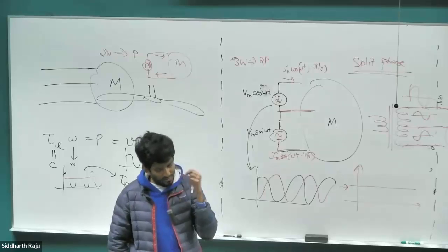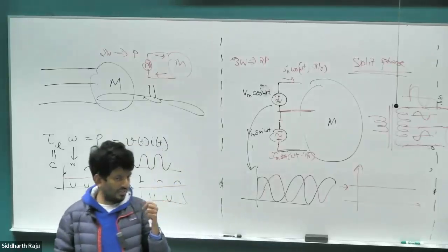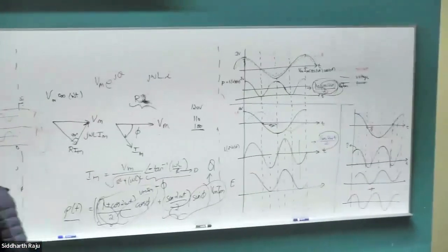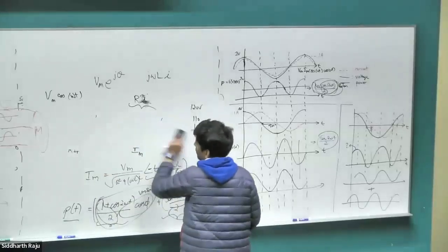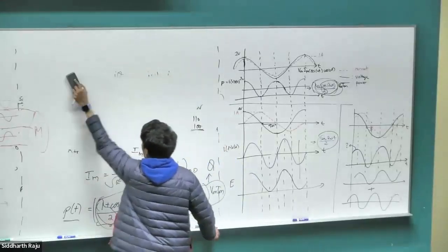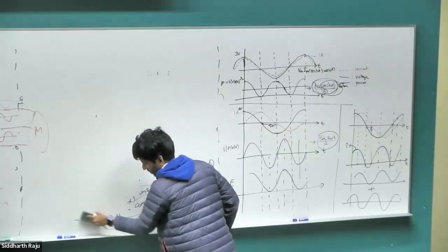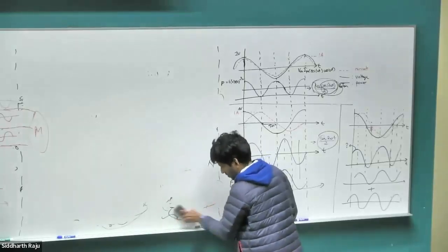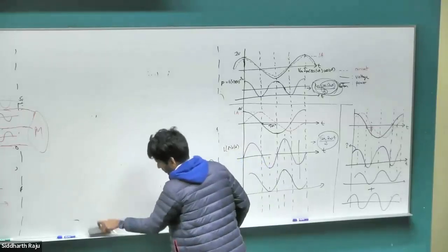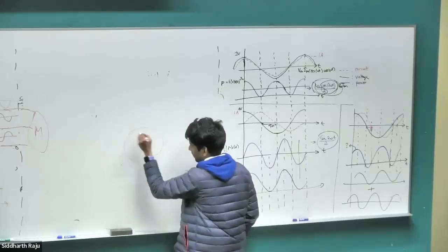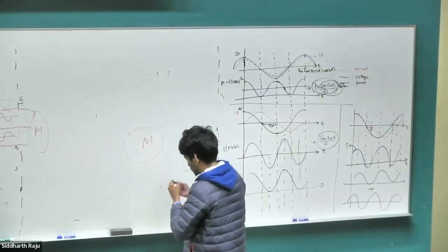Right? If I go to a 3-phase system, how many wires do I need? Let's assume it's completely balanced. 3 wires. For our motor, all the windings hopefully are balanced. In the advanced mode, we look at cases where the phase becomes unbalanced. It will cause some circulating currents in delta motors and so on and so forth. But for our case, we're going to assume all the phases are balanced. So we have a motor, I shouldn't be using red.